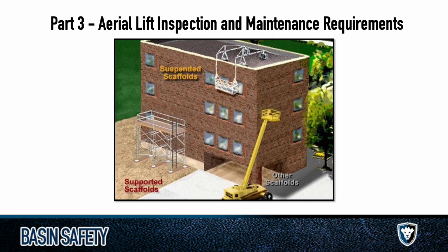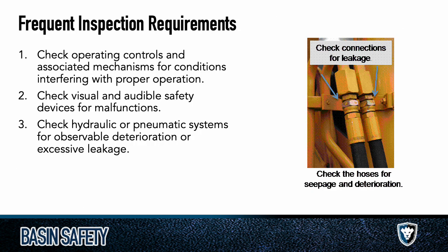So inspection and maintenance requirements. I'm going to go through this pretty quick, mostly on the frequent side. So frequent is typically a daily check, right? You're going to make sure there's no leaks at the anchorage for the hydraulic system. You're going to make sure that the backup alarm works, or that in a lot of these cases, these have front and back alarms. If it's moving, it's beeping at you. You're going to check the operating controls, make sure they're not jumpy, make sure that they're smoothly working and they actually reach the maximum intended limit.